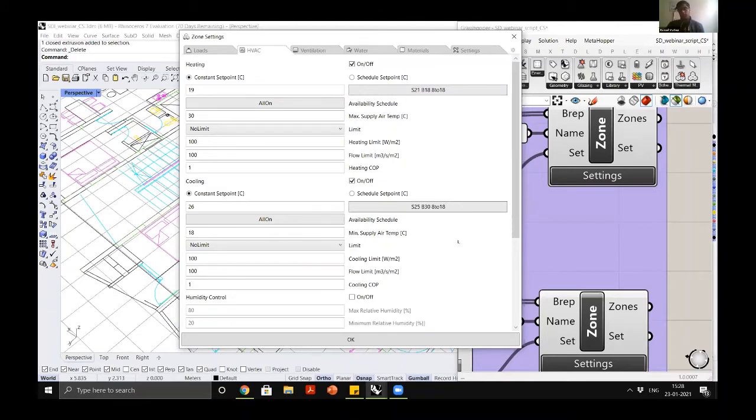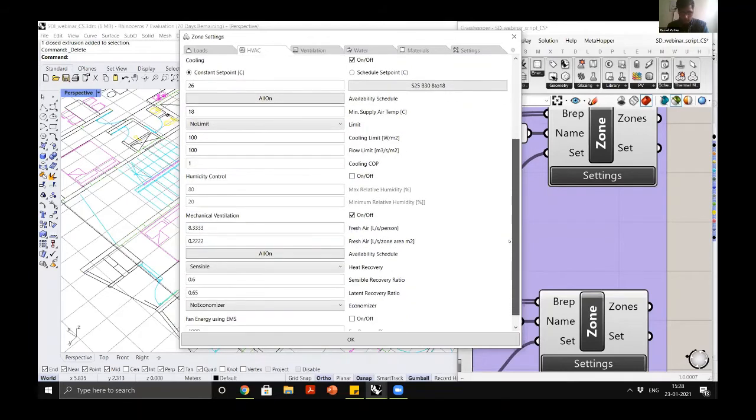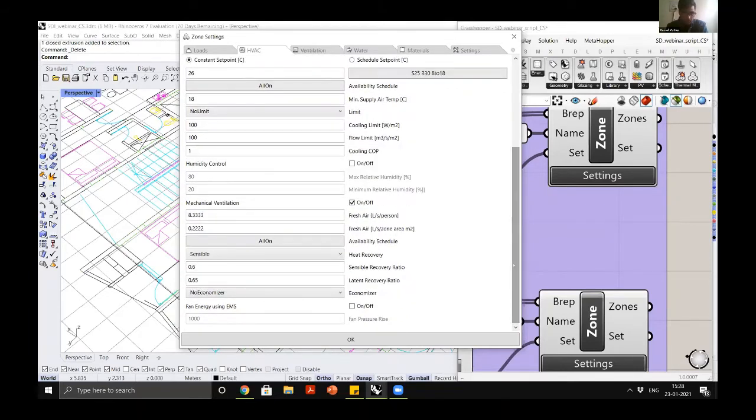So if you go by a standard split AC, the COP would be around 1.2. And if you switch to a higher efficient chiller, it might even go up to 5 or 5.6. So you can check these specifications in the model. And just for the sake of brevity, you can avoid other parameters. You can just take assumptions on the COP and move ahead to understand how much energy your system is saving.